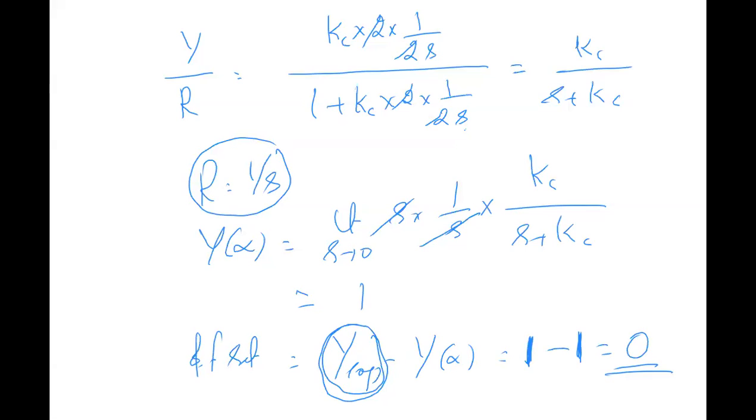Not 60, because changing the set point means you intentionally want to operate the reactor differently. Set point is something which you are giving. Load changes come because of a disturbance. Load is a disturbance, set point is not a disturbance. So if there is a change in the load, the system will make sure that the value becomes 60 again.